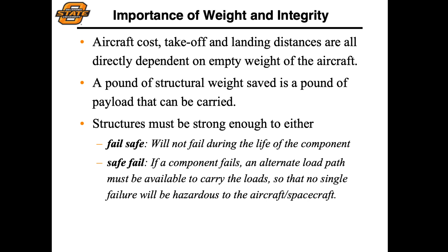That's going to be not only mandated by things such as the FARs, but really driven by basic design considerations. As your aircraft gets larger and uses more material, that cost is going to go up. And what we'll typically see is that saving pounds on an aircraft can maybe save thousands, tens of thousands of dollars per pound on the overall cost of the aircraft.